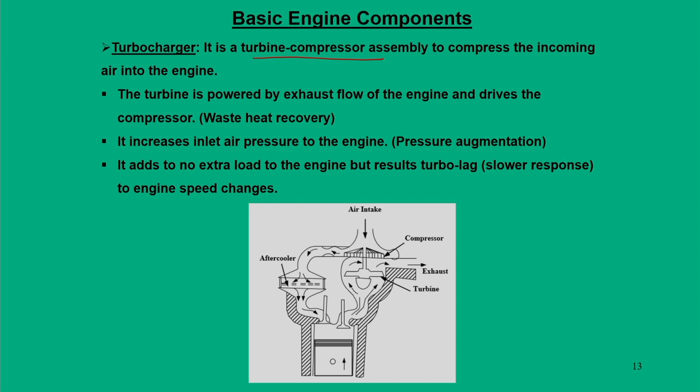A mechanism is thought of in which the turbine is powered by the exhaust flow of the engine, and this turbine drives the compressor. The turbine does not take any extra power from the main engine block; rather it taps the heat or energy from the exhaust gas and that runs the compressor. So, it does not add extra load to the engine. That is the main difference between a turbocharger and a supercharger.